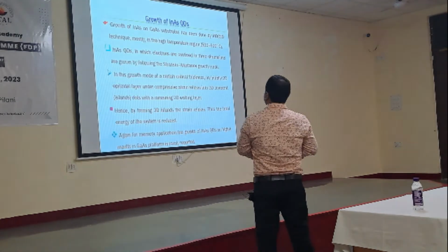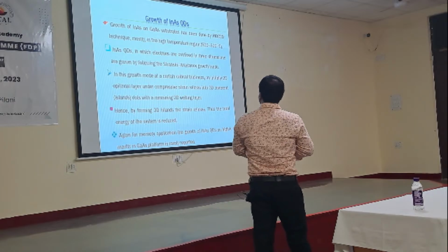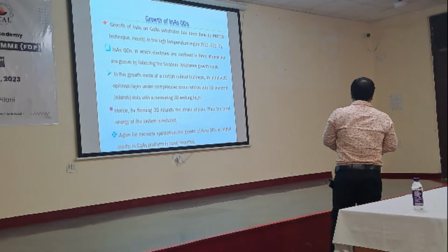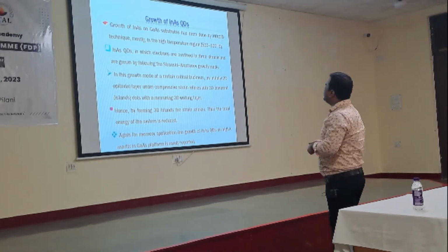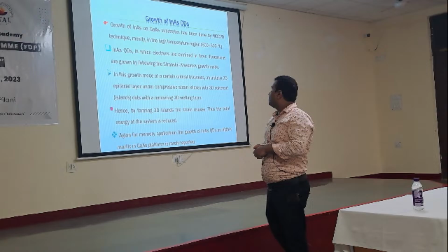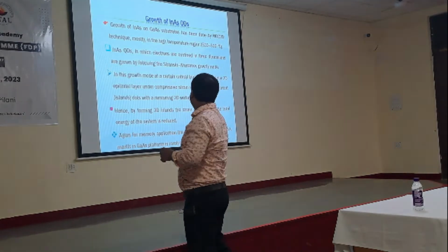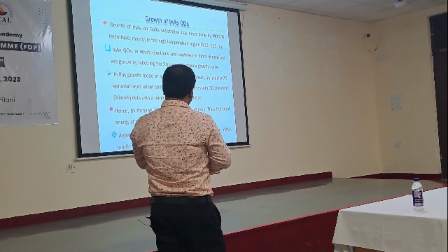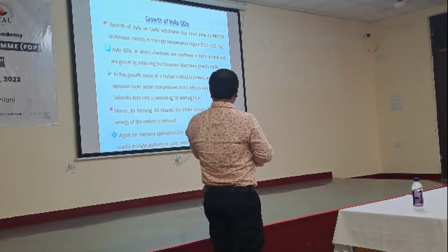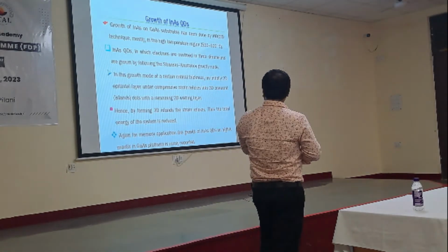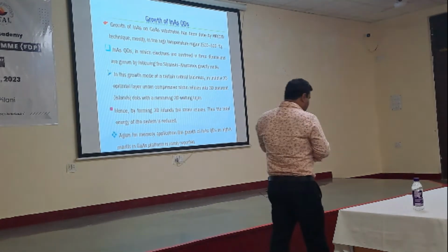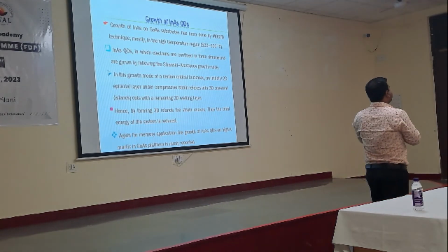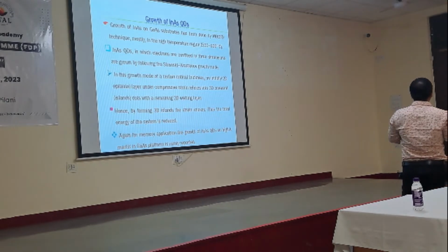Next. Now growth of indium arsenide. Basically if you see the epitaxial thin film deposition techniques, there are so many deposition techniques. One is the Volmer-Weber growth mode, and the second one is the Stranski-Krastanov growth mode. Here I have used the Stranski-Krastanov growth mode because in this growth mode, basically at a certain critical thickness, initially 2D thin films form, but that 2D thin film is situated in a very highly strained condition.